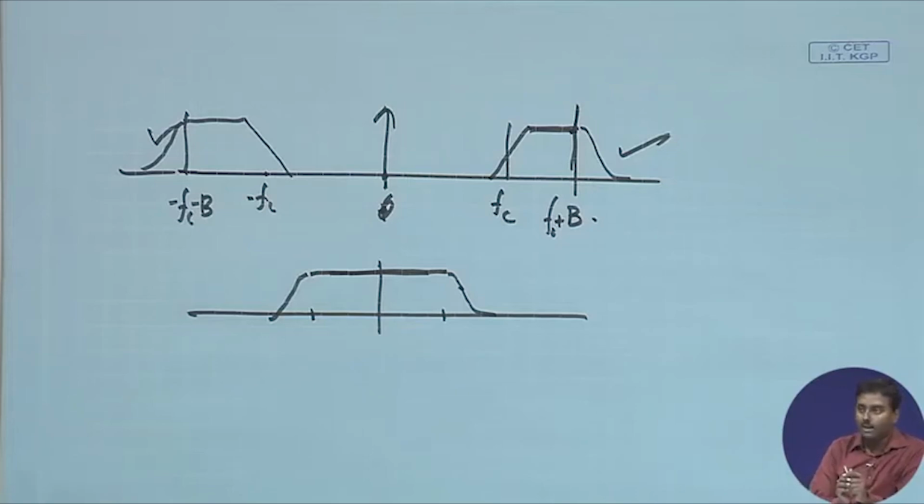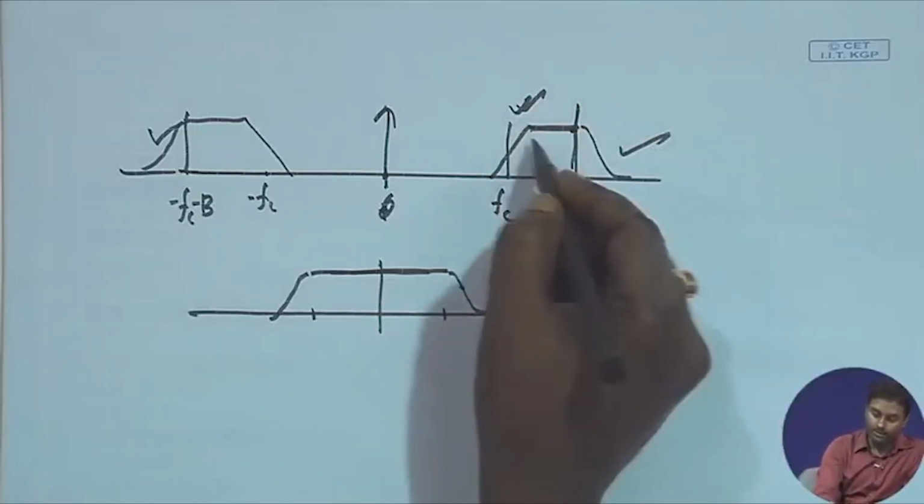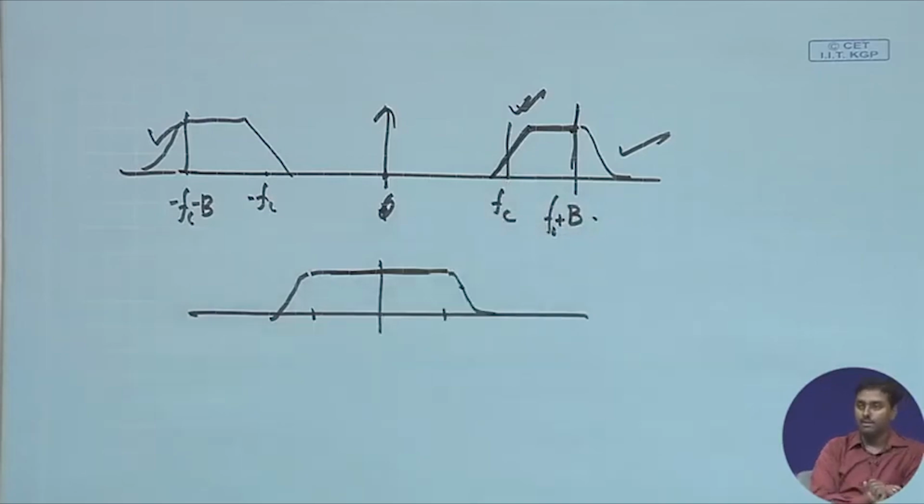That is how VSB signals are generally generated. All you have to do is employ this filter and characterize the roll off properly, whatever roll off you wish. Now, regarding the roll off, it depends on what kind of circuit you can choose, and accordingly there will be a trade off of how much bandwidth you take.